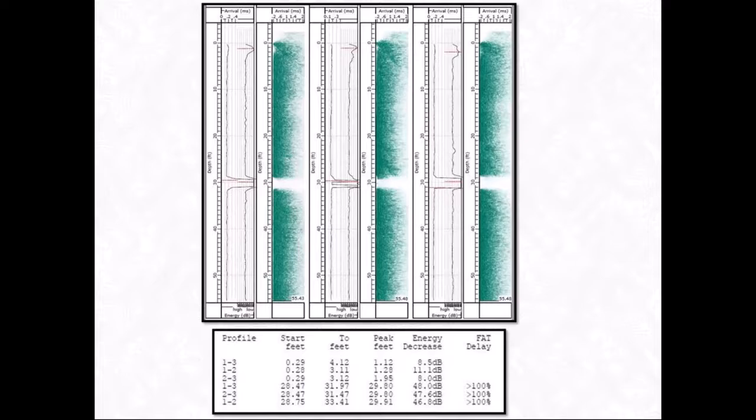Here's another example, some data. And you can see in this example here, you get down to about 30 feet and there's some sort of anomaly there. The data isn't consistent. So that's an indication something's going on there. And in cases like that, sometimes the engineer will require to take a core of the shaft to try to find out what's going on down at that 30-foot depth.